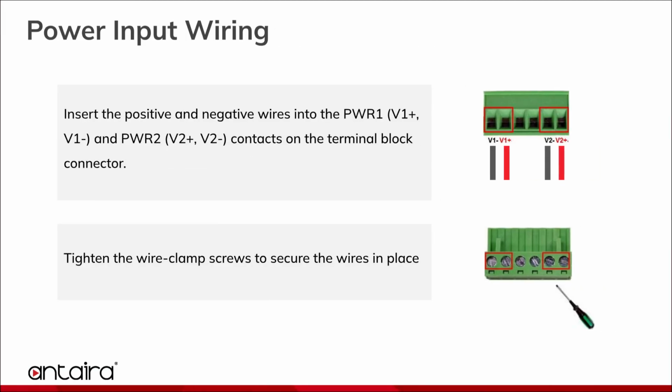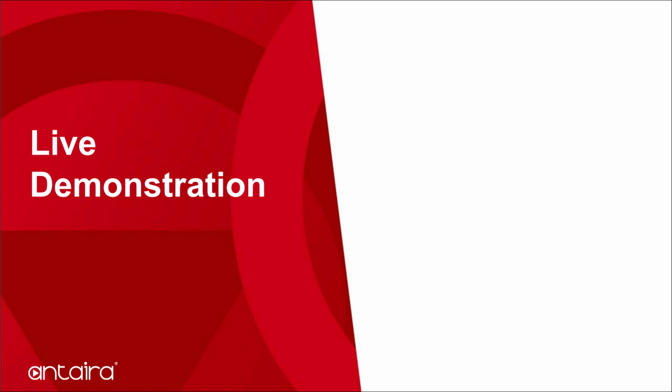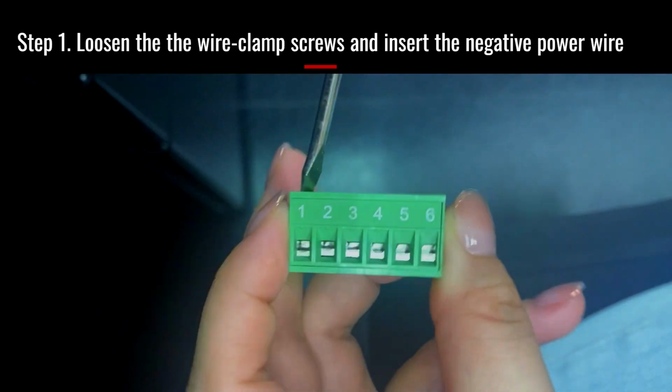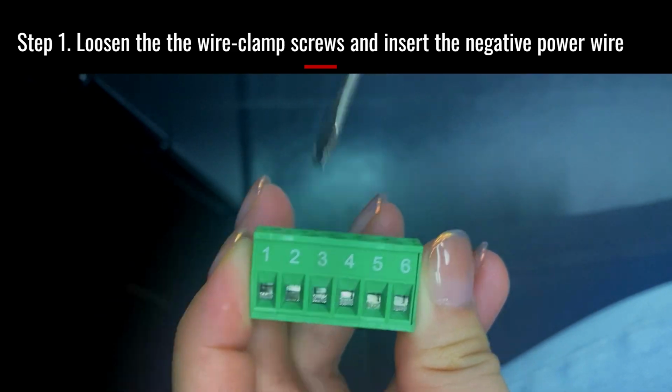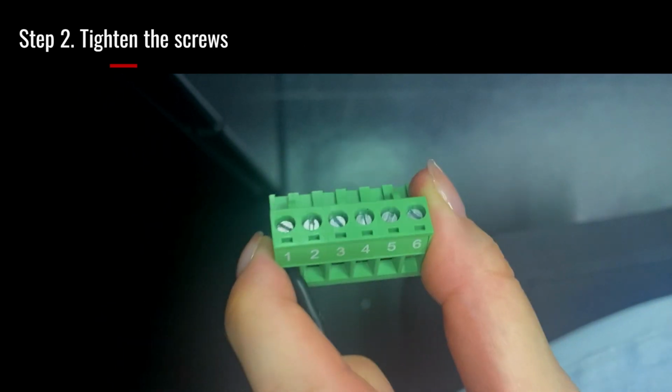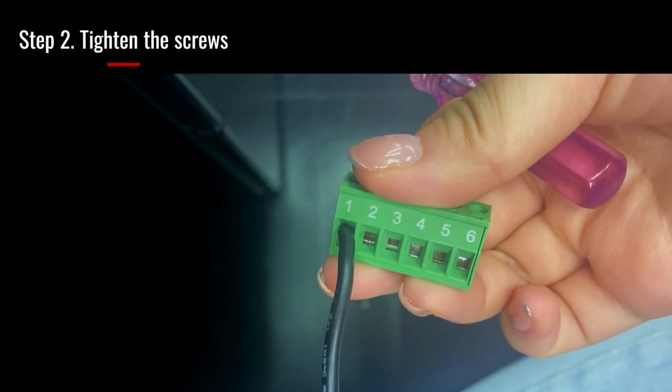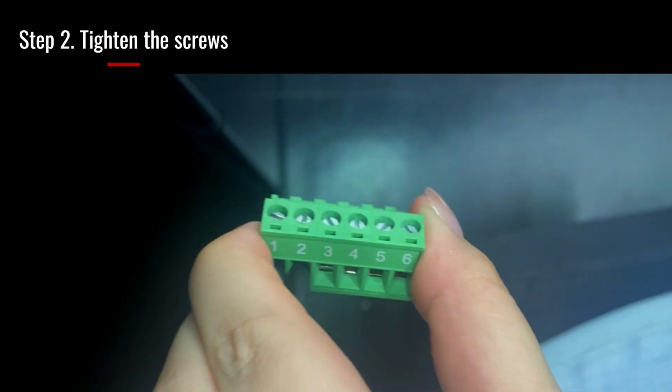To connect the power supply to the switch, you need to insert the positive and negative power wires into the power 1 and power 2 contacts on the terminal block and tighten the wire clamp screws to secure the wires in place. The following is a live demonstration. Step 1. Loosen the wire clamp screws and insert the negative power wires for power 1. Step 2. Tighten the screws. Repeat these steps for the positive power wires and power 2.